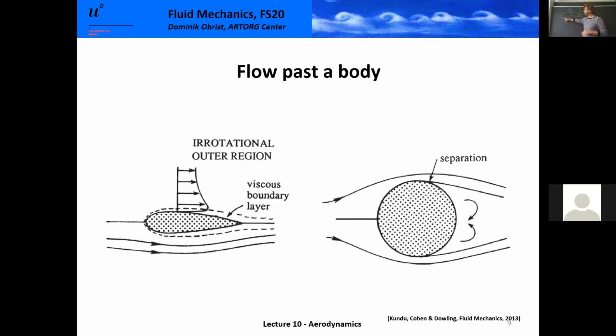Now, the thing that we call friction drag, so the drag due to the friction, I think that should be quite obvious. This is the drag exclusively due to the tangential shear stresses. So on the blackboard, it was the red or orange tangential shear stresses, which only come due to viscosity, and potential flow theory, which does not have any viscosity in it, completely neglects that. So that is the friction drag, and that is one contribution to the total.